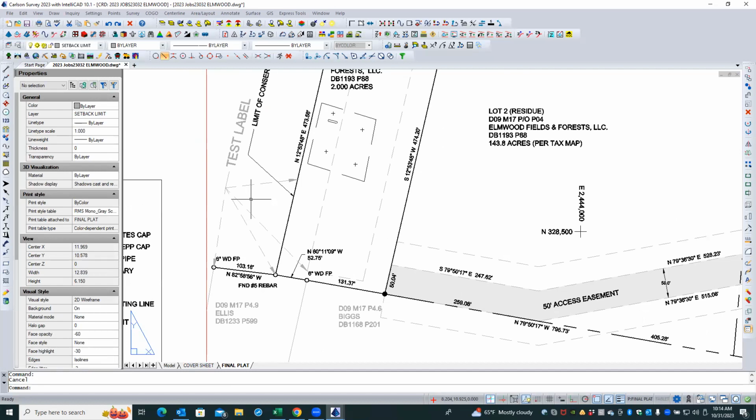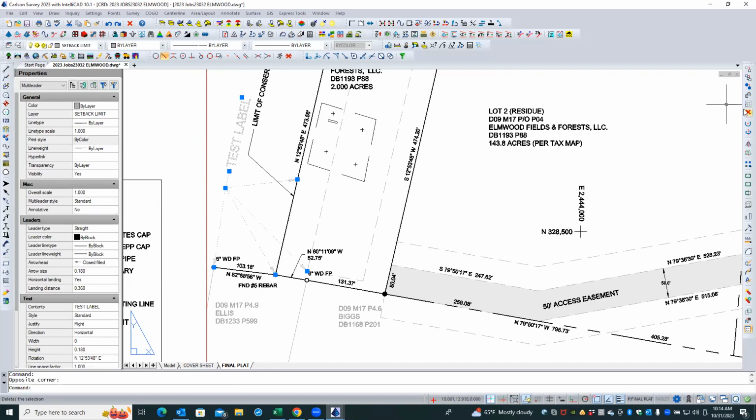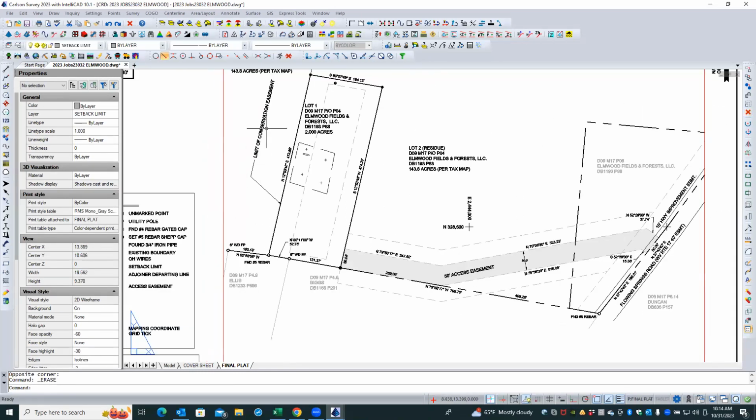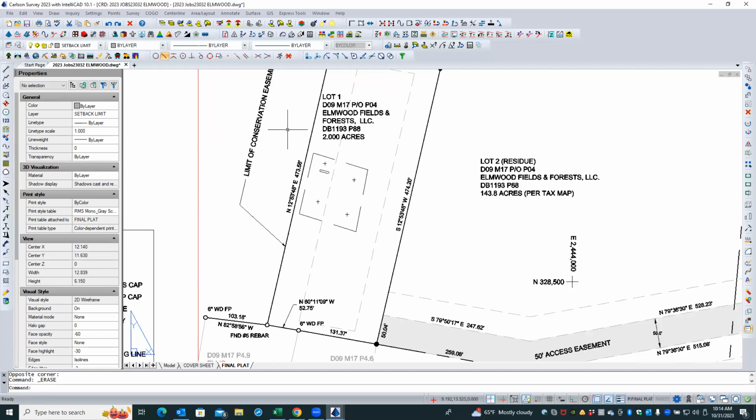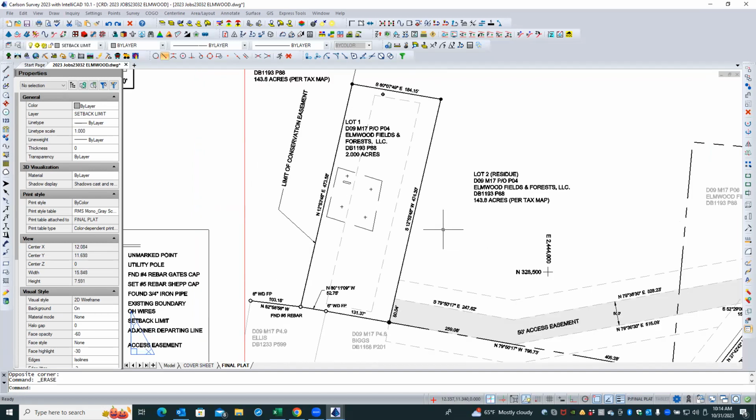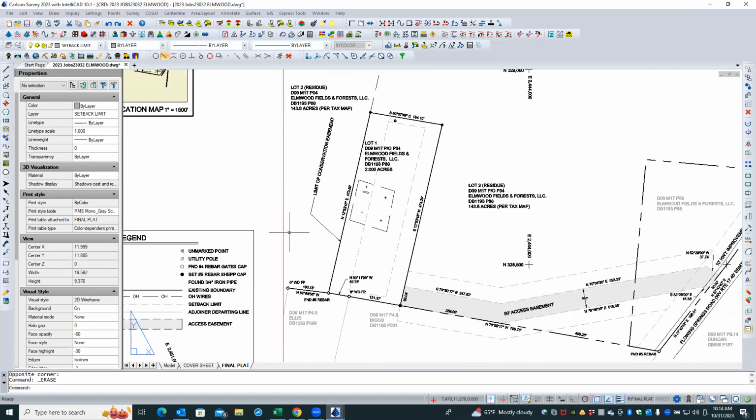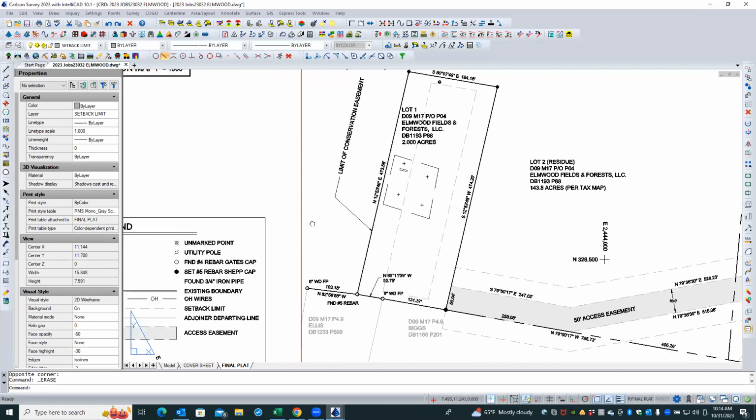So it's a really nice and versatile thing, but you don't want to have to go around changing, rotating this and the other. You want it to be parallel to that, or it's going to be perpendicular to the page. Now, there's a way to make that happen when you go to create this, even in your temporary paper space, is if you do a twist screen.